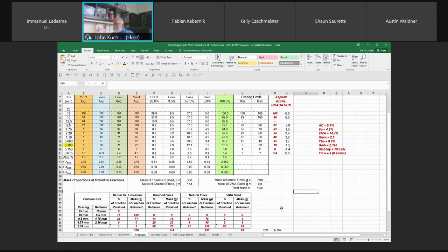But it's the same thing as MI did one time. Their concrete strengths for when they're doing highways is phenomenal. It's way too brittle. And their reasoning was that when they used to do concrete testing, they would find out that they would always get 7 to 8 MPa greater at 28 days in their mix design. So they said, well, in their infinite wisdom, if we're getting 7 greater, let's just specify that much greater. So let's say instead of having a 32 MPa mix or 35, they said, let's go for 42.